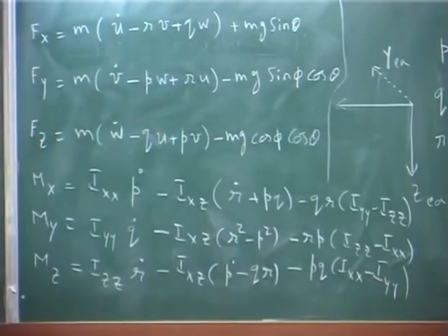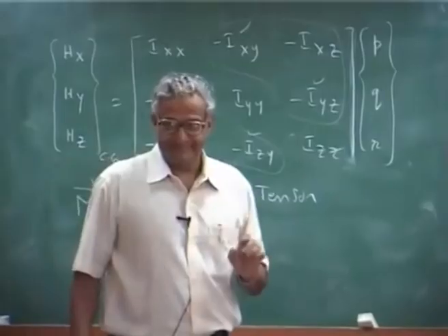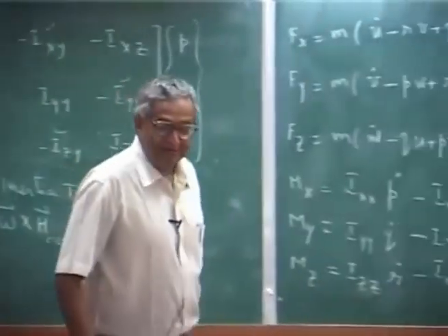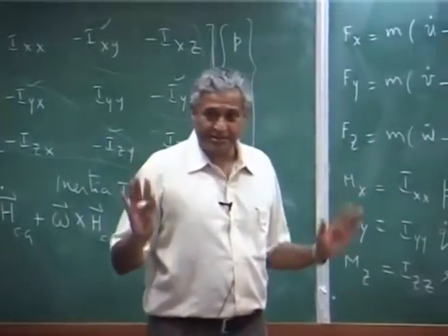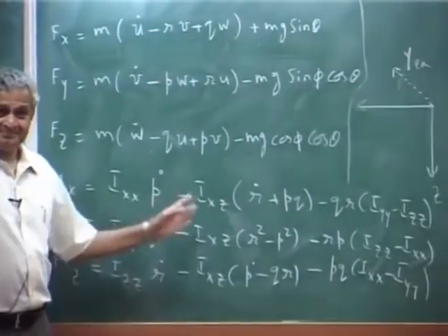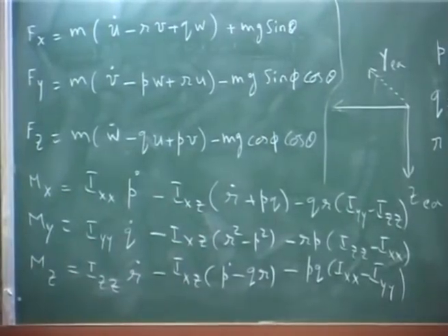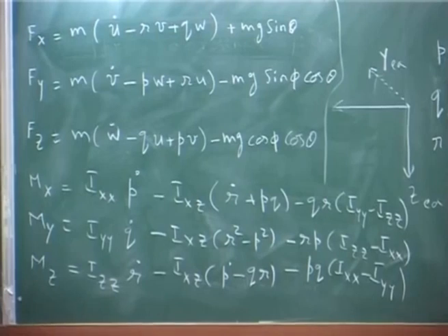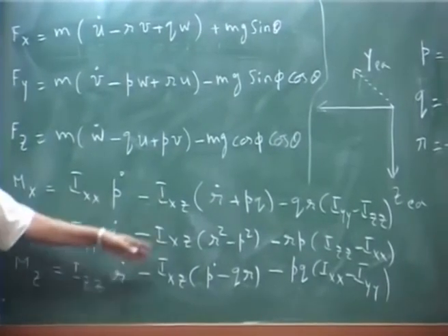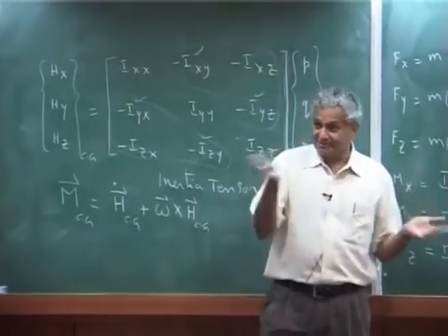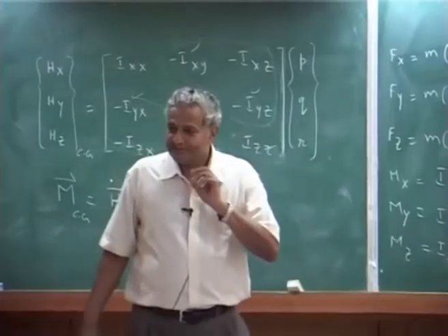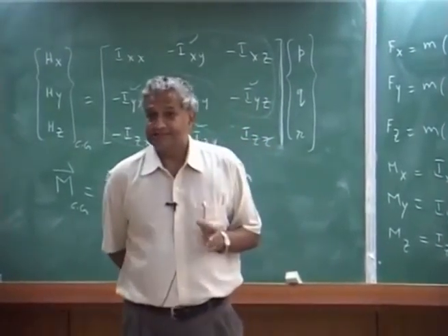Okay. These are my equations, and normally you see IXZ is comparable to IXX magnitude wise. That is why the weights and CG group in any aircraft or aerospace company has to get these values, okay, before the aircraft is built. You make an estimate from the drawing and then calculate the complete IXX, IYY, IZZ, all these numbers for a given coordinate system, because if you make a mistake there, your flight dynamics is all wrong. Sometimes it is a routine job, but one has to do it in an aircraft industry.